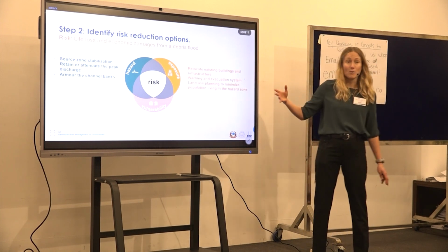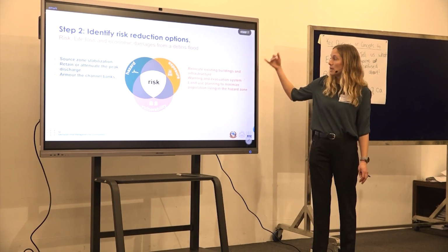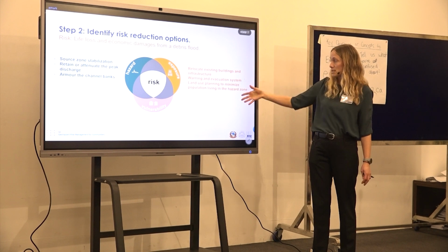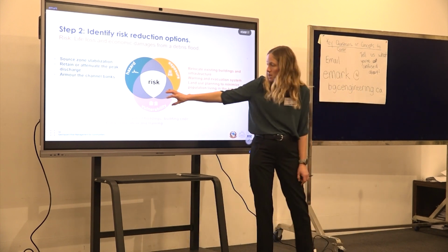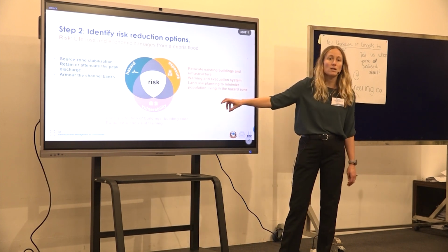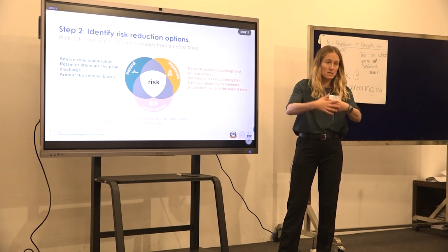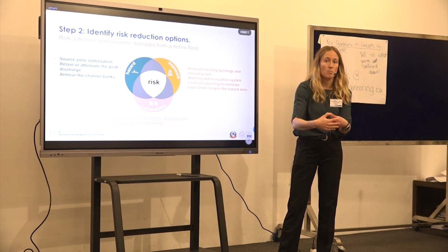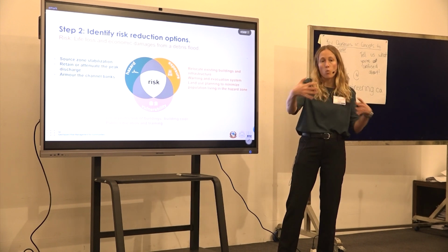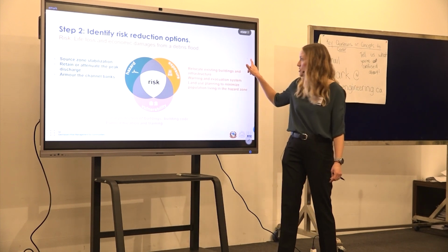Exposure, in theory, if you had all the time in the world, you could relocate the buildings and infrastructure. You could use a warning and evacuation system, or maybe land use planning. And then vulnerability reduction would be things like, what can you do at the building level to reduce the susceptibility of that element at risk to the hazard? That's things like local protection, building the building stronger, putting a wall around the building, increasing the height, and also public education.